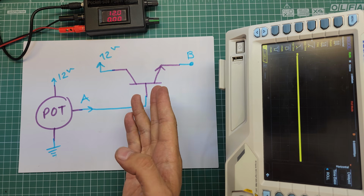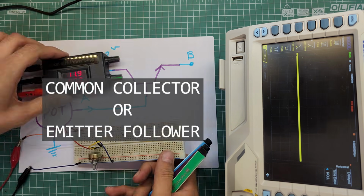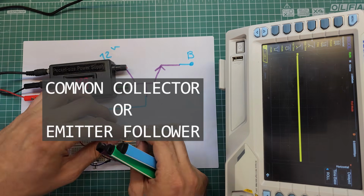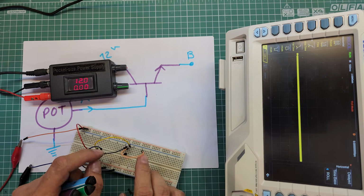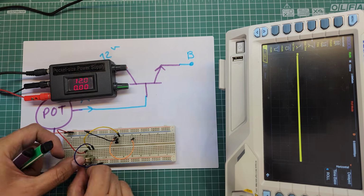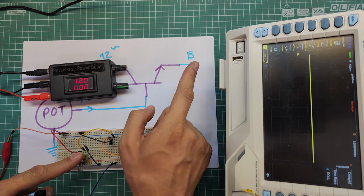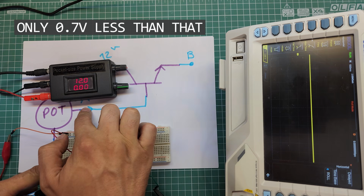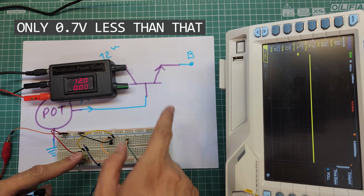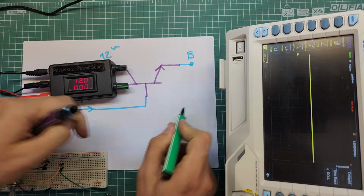This configuration of transistor is called common collector or emitter follower. The voltage here on point B is almost equal to the voltage on point A, but it is much stronger. Let me connect the DC motor to point B and see what happens.